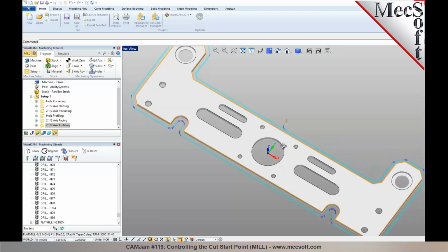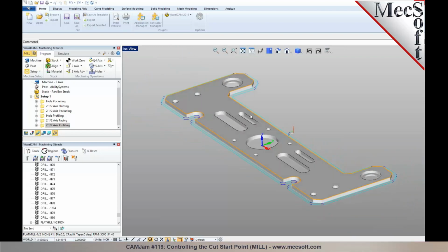In this particular example that you're looking at, you will notice that it determined this as the longest side because these two sides have some notches in here. So it figured out this is the longest edge. It does not have any cutouts. So since the start point is over here, the entry and exit is being applied at the start point.